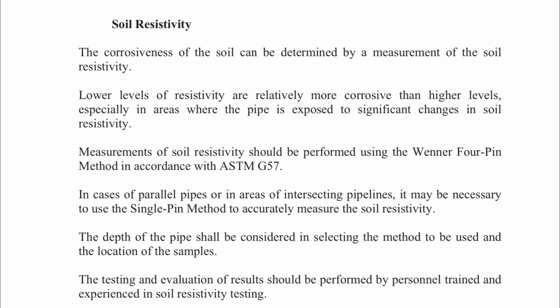By googling you can understand very easily what the 4-pin method and single pin method are. The depth of the pipe shall be considered in selecting the method to be used and the location of the samples. Depth of the pipe is very important in this case. The testing and evaluation of results should be performed by personnel trained and experienced in soil resistivity testing.